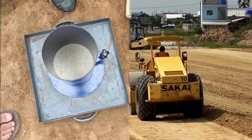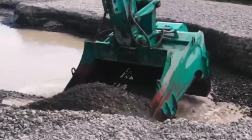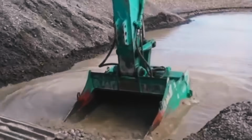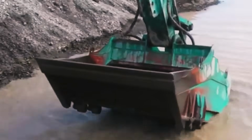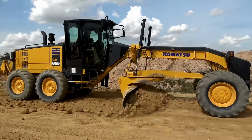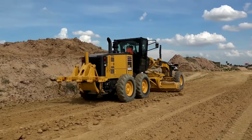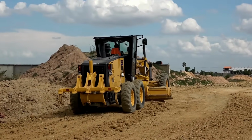The specifications to be followed for subbase are as follows. The selected blend shall be free from organic materials and shall have a minimum soil bearing capacity of 2 and above. Normally, good granular subbase materials have a bearing capacity greater than 3. The grading of material shall conform to the designated sieve analysis. The maximum size of granular material shall pass the 75 mm sieve, meaning that all particles used in subbase shall be less than 75 mm in size.